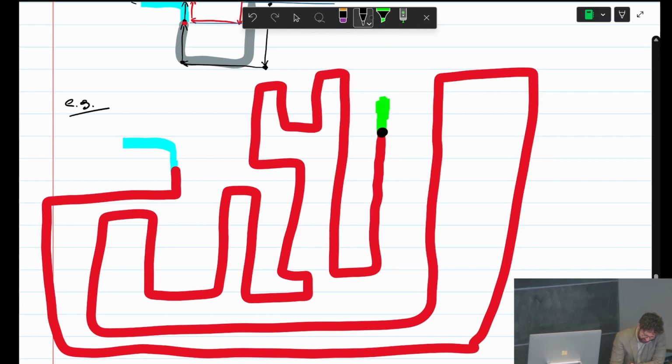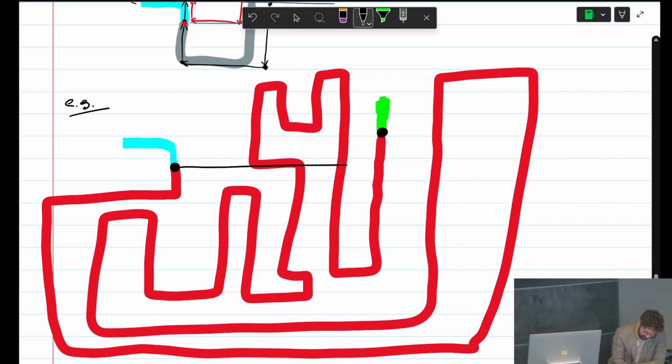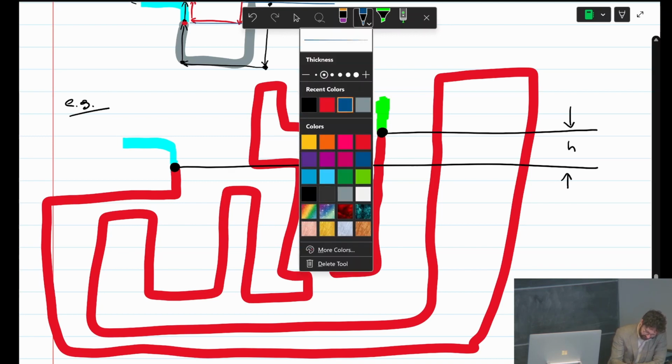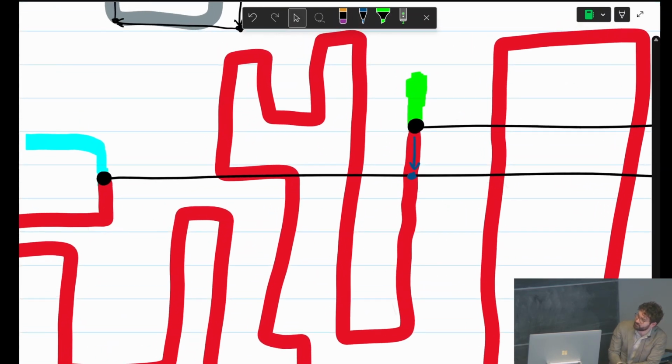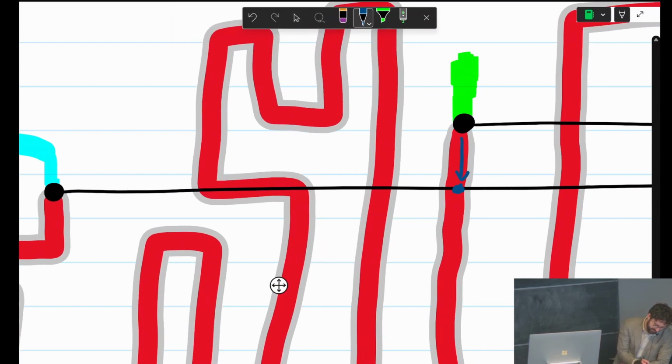Say we're trying to go from here to here. All that matters is the height difference between those 2 points. You don't have to go through every single length of tubing to get there. So the only thing that matters in this problem is this height h. So if I give that to you on an exam, I highly recommend going straight across. Again, the core concept here is that all you have to do is calculate that small amount of pressure gain there, and then you can move horizontally. Because those points are at the same height and the same connected fluid, you can move directly straight across.